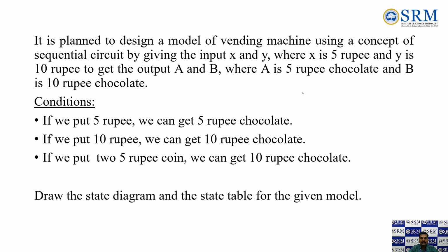Now we are going to discuss the topic of vending machine model. We are going to design a model of vending machine with the concept of sequential circuit by giving the inputs x and y, where x is 5 rupee and y is 10 rupee, to get the outputs a and b, where a is 5 rupee chocolate and b is a 10 rupee chocolate.